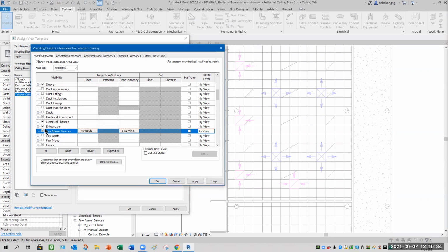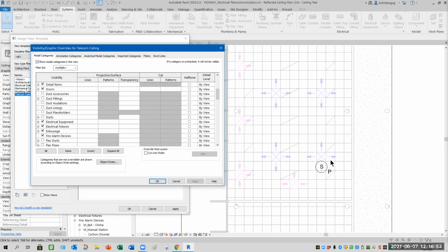So remember to take note, not just the view range. Because early on, we created this from where? From the electrical plan or electrical ceiling, but we set it to telecom. So we need to configure. Now you're showing us only, right? We don't have to insert here because we're making a fire plan. So actually, this one should be on the fire side.